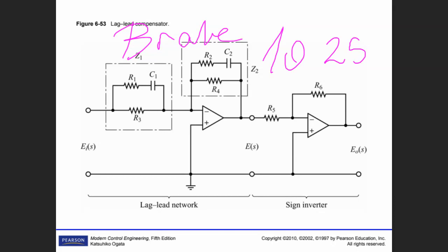I'm just going to review the lag compensator and lead compensator. For lead compensator, if we are not happy about the transient response, we add a zero and a pole to this system, but the zero is near to origin and the pole is far away from it. And how could we calculate? We repeated that several times, and you have a home assignment.